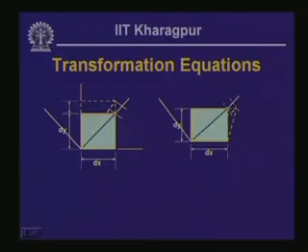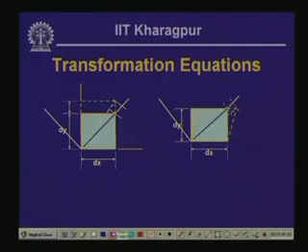Now, let us look into the situation what happens if it undergoes strain in the y direction and thereby the shearing strain. When this particular element, having length dx and dy, undergoes strain in the y direction, this is the x axis as we had defined, this is the y axis, and as per our definition the diagonal of this element represents the x dashed axis and perpendicular to that is the y dashed axis. So, this is the angle theta,